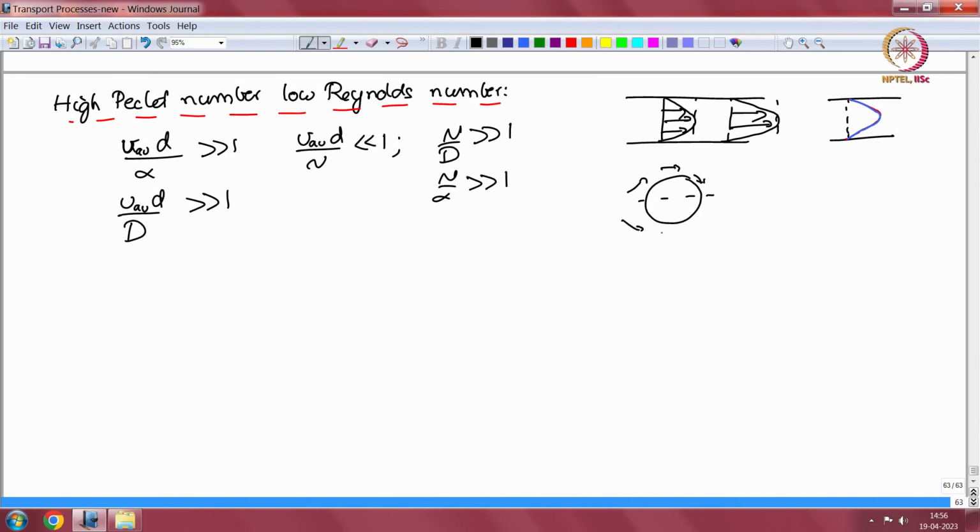At each point on the particle, or at each point in the velocity profile, if I change the free stream velocity, the velocity direction is the same at each point, only the velocity magnitude increases by the exact same factor. That is, if I increase the free stream velocity by a factor of 2, the velocity at every point increases by a factor of 2.